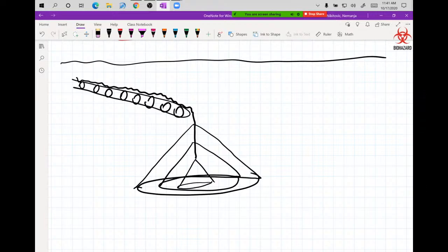Well, you say, well, that's easy because you can just create a shutoff. Yeah, but let's talk about the engineering of the shutoff, because it's stone, it's gravel, it's corn, there's a lot of dust, so you can't put a light sensor at some level because very quickly that lens is going to become dirty with dust and so on.